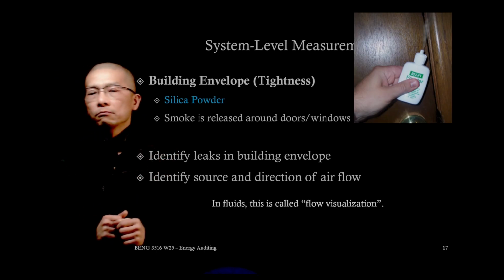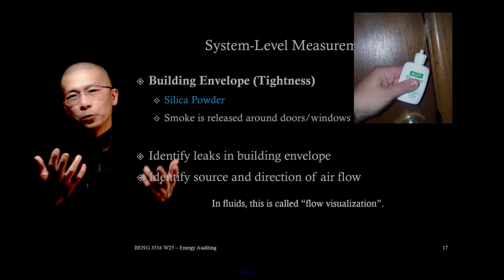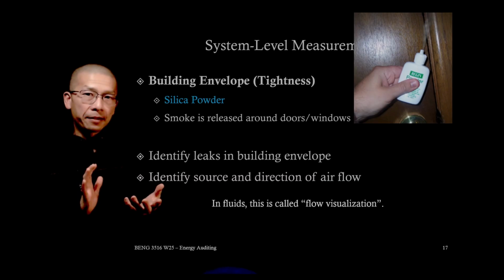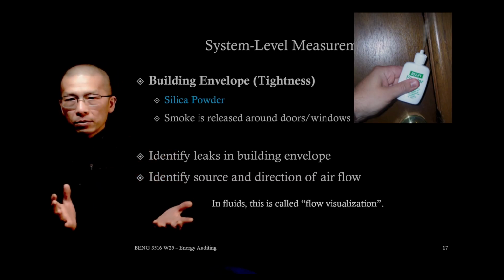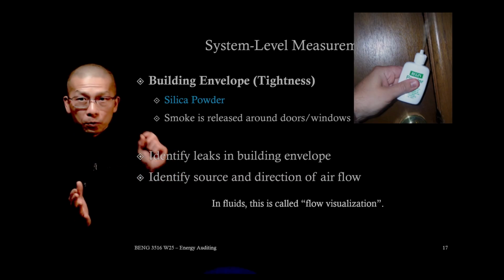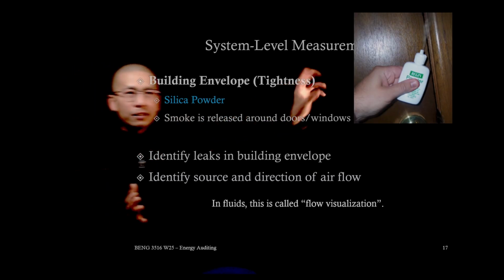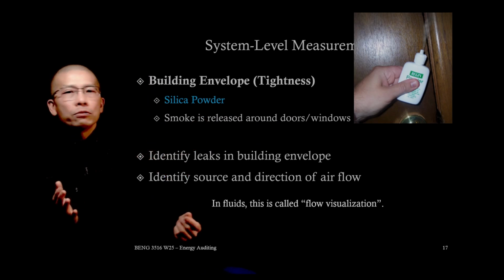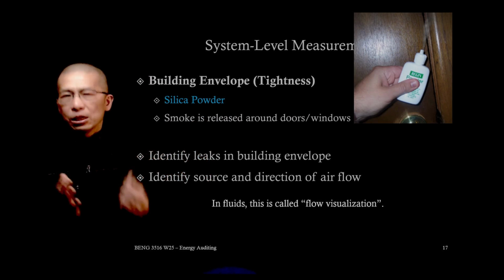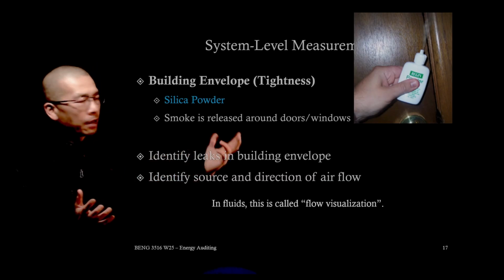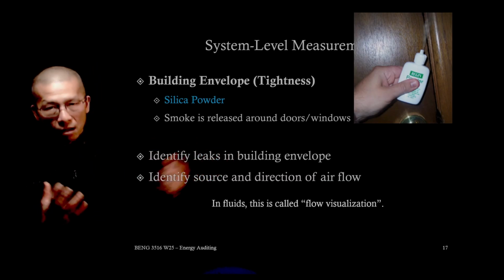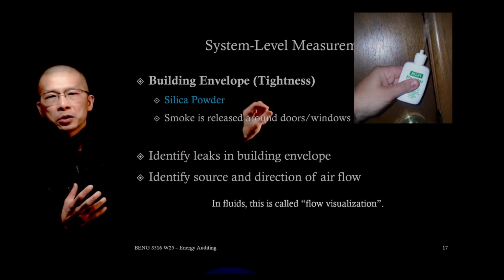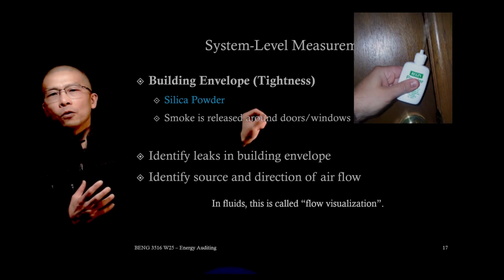Air leakage, right? We know we cannot see air, we can feel air. If there's wind, we can feel air, but we don't see air. So air leakage is invisible unless you make it visible. So we can use the smoke. The smoke test shows direction, magnitude, and location of infiltrations. This is essential for envelope diagnostics, right? The hand you see now is applying powder smoke and it's testing for air infiltration.